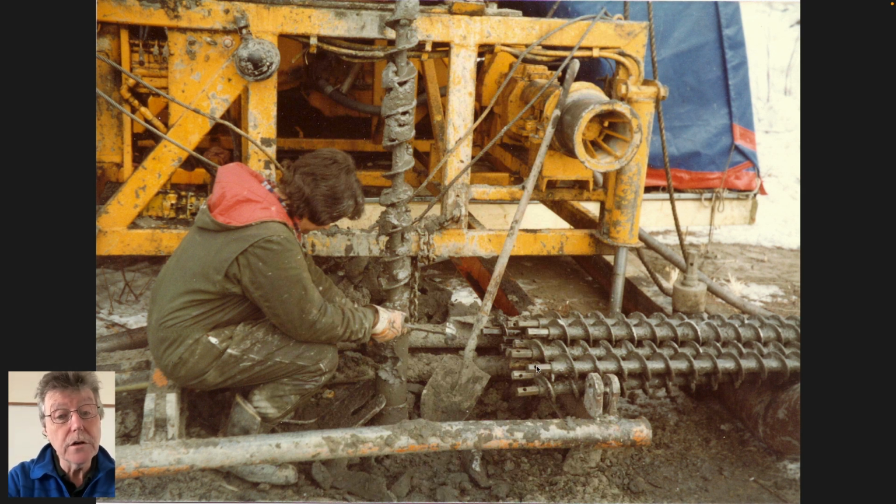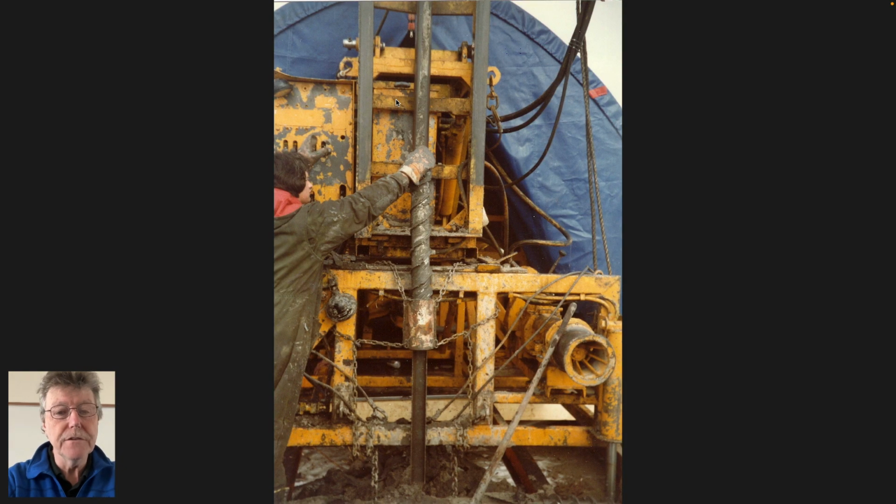And a solid stem auger. So male and female couplings for the auger with a clip going through it to join them. Drilled into the ground, it brings up soil on the flights. You can sample at the surface. You can't sample from downhole unless you pull all the auger flights, leaving an open hole, and then sample using, if this is a clay, a thin wall sampler, which it is, or if it's a sand, a thick wall sampler.